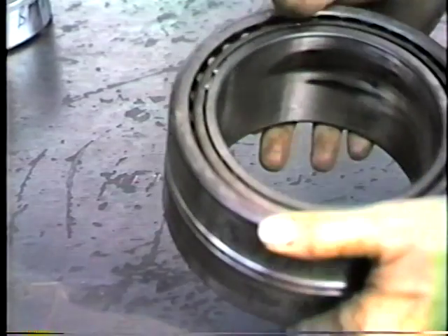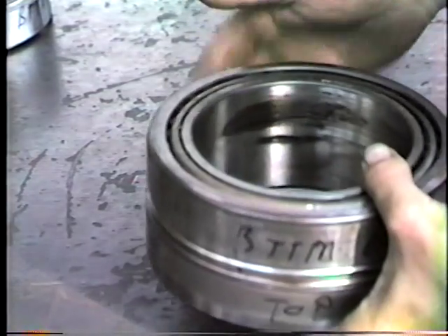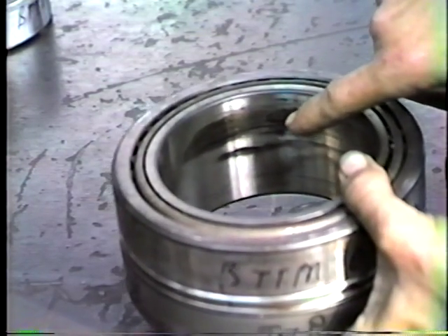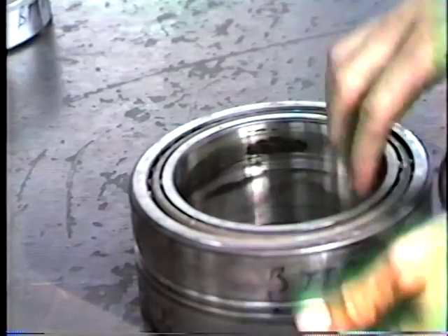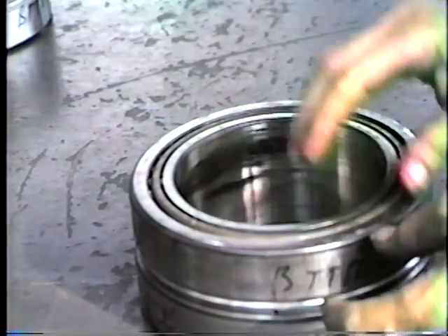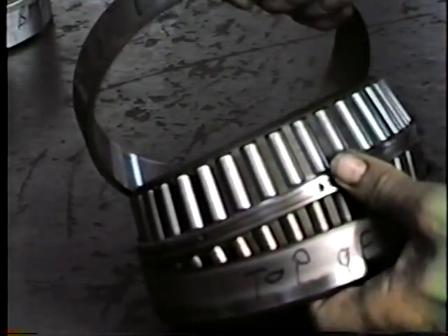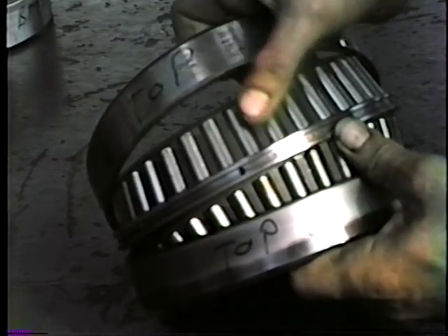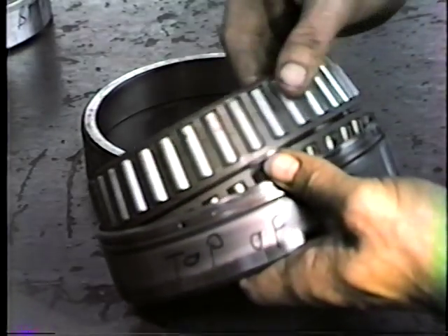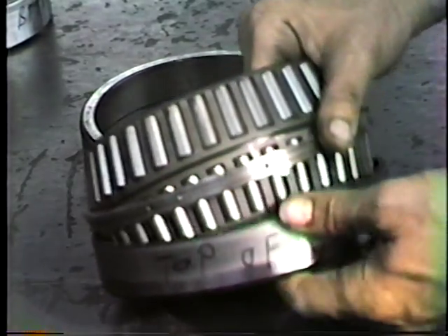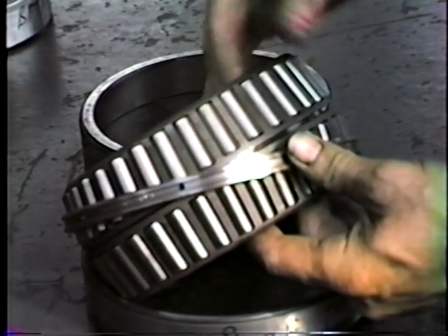The upper bearing had a lot more play in it. Point to that mark on the inside there, right underneath your thumb. Yeah, good. Turn it around, drop it down a little bit. Okay, that's good. You can pretty well see that. There's no scars on this bearing, nothing other than just the end play wear.